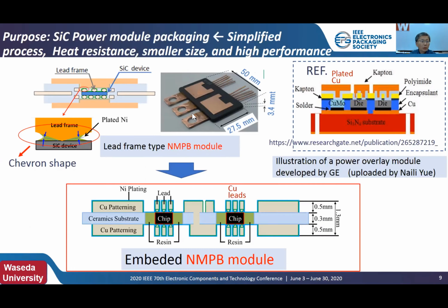Compared with the conventional embedded power modules or the power overlay packages, this technology is advantageous in application to high power devices and simplifying the packaging process. This method can eliminate the lithography, sputtering, and long-term additive deposition process for forming the interconnection.